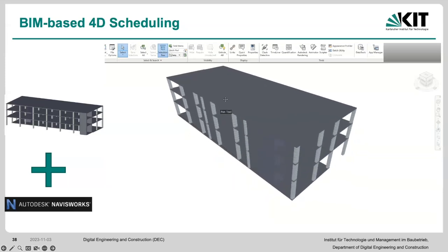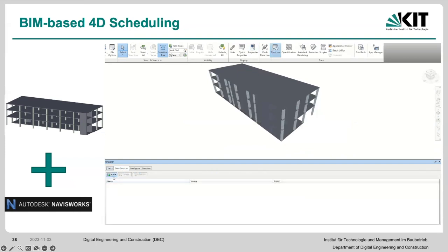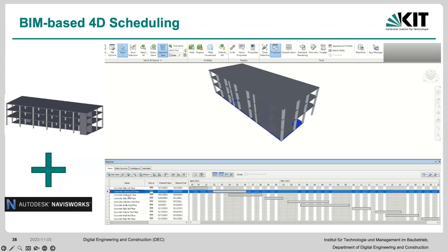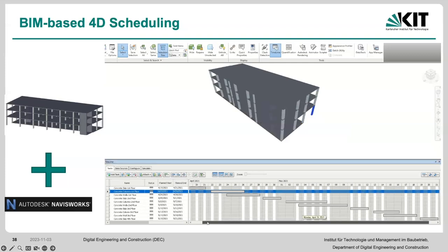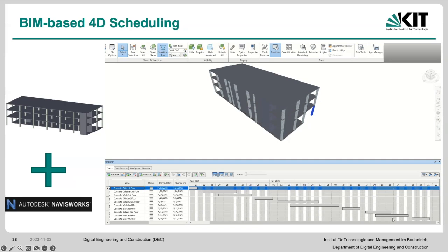And for this, you have basically your elements. Now what you would need to do is assign, for each and every one of these objects, production activities, and it depends on the level of detail that you're going to be modeling this at. And using the detail that you're going to be having, what type of schedule and what kind of duration you're going to be assigning to each and every one of these activities. So it requires two basic aspects. One is the order of the activities, basically the work sequencing, and then the second part is the duration, right?